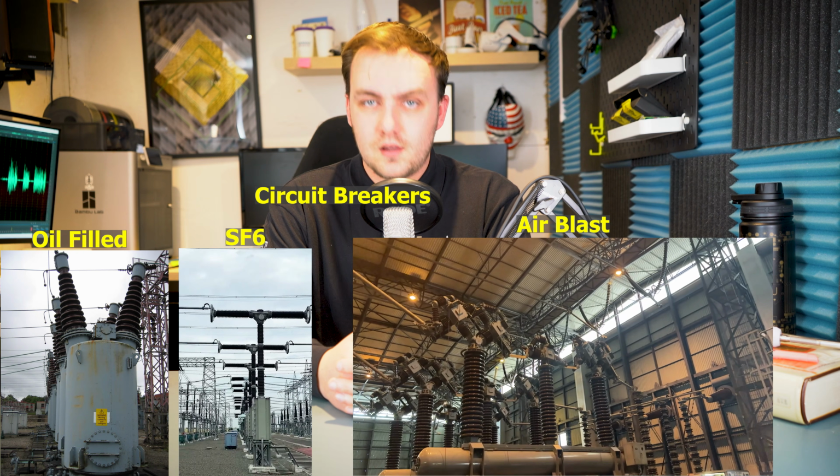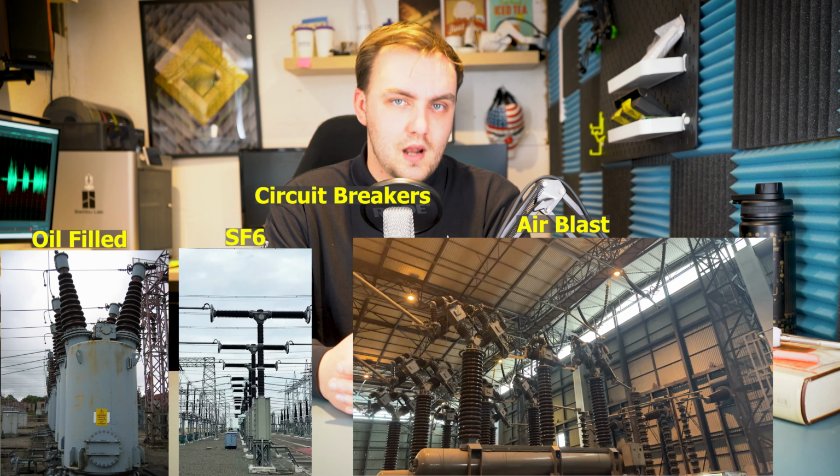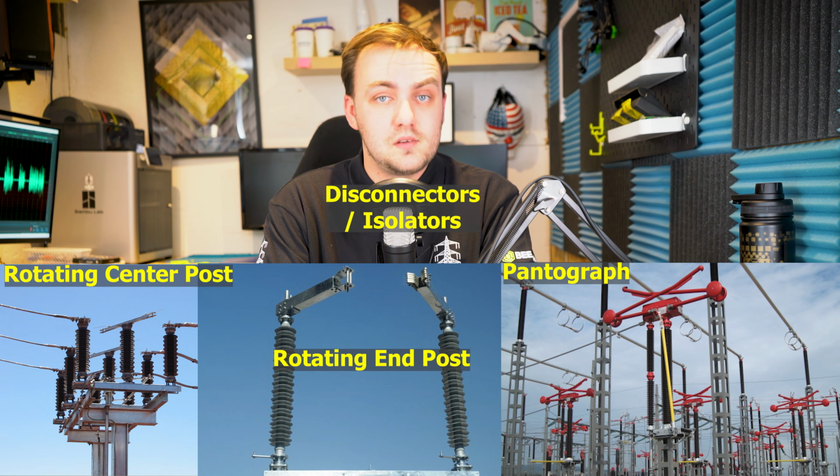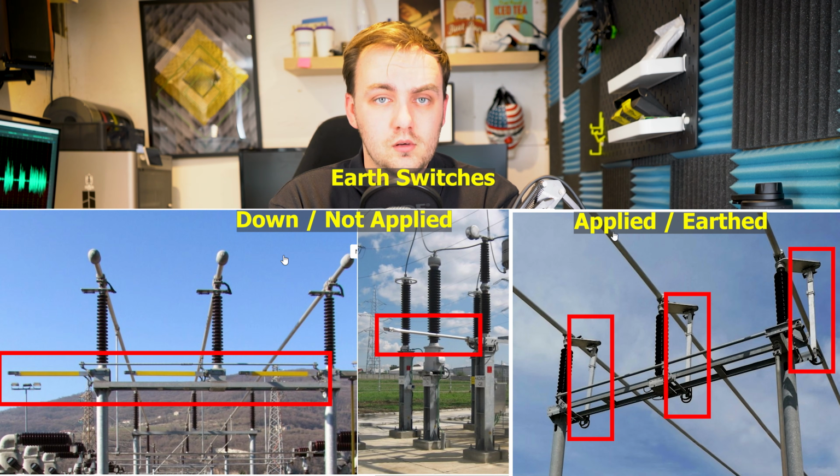Substations contain switchgear, like circuit breakers and disconnectors, which let us reconfigure the network and send power down different lines or break the circuit when a fault is detected. And earth switches, which make the system safe to work on and remove trapped charge from the system.